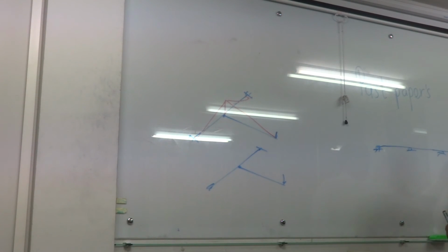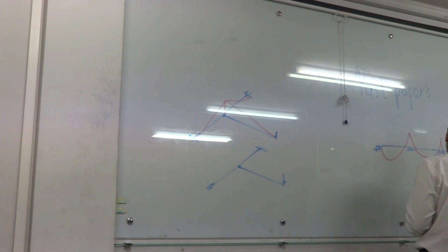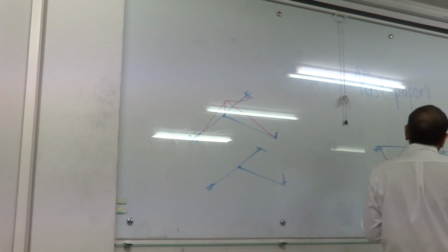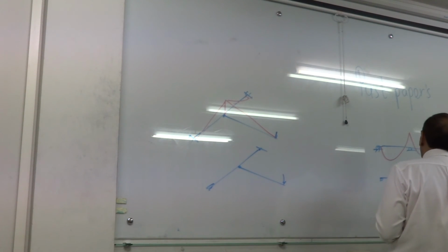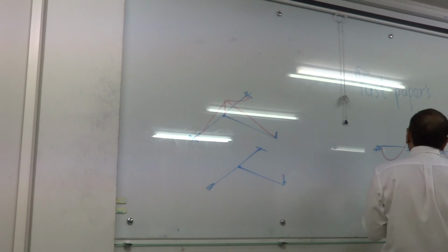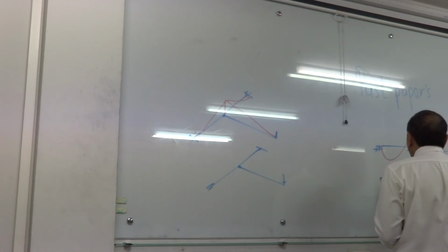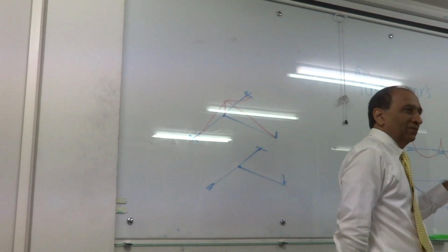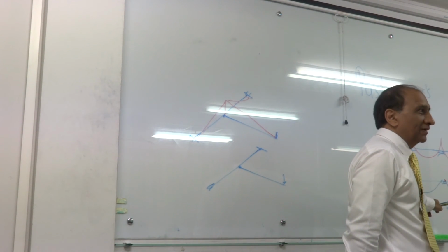This is a beam, correct? What is that? Bending moment diagram, correct? Right. Suppose I say that, okay, and one more. I say that, okay, I have hinges here and I have hinges here. I do not have any negative moment capacity. So the bending moment diagram will be like this. But the beams are not falling down. So even if I do not design for negative moment, I do not provide any negative reinforcement, the beam will become like this. The positive moment will increase, but it will not fall down.